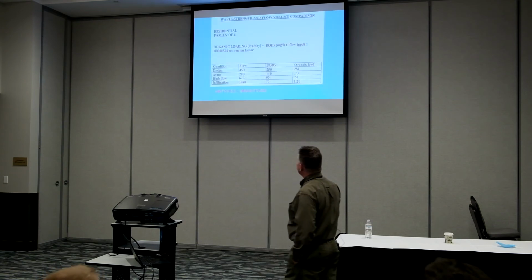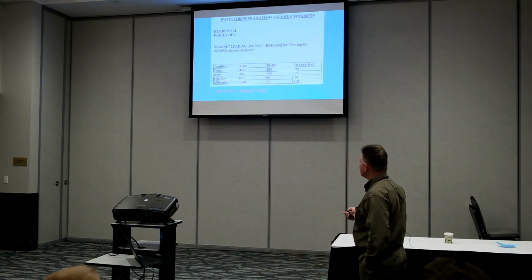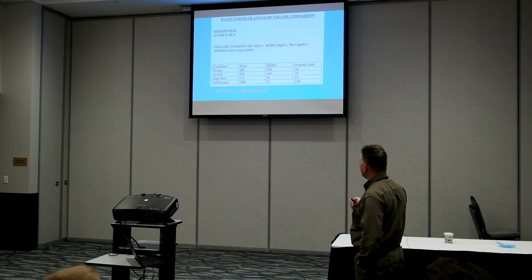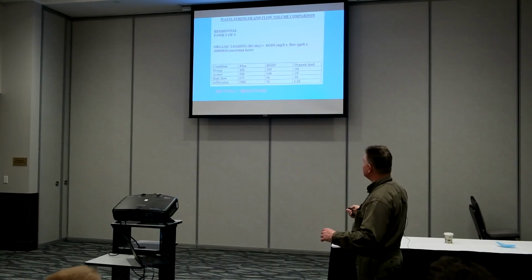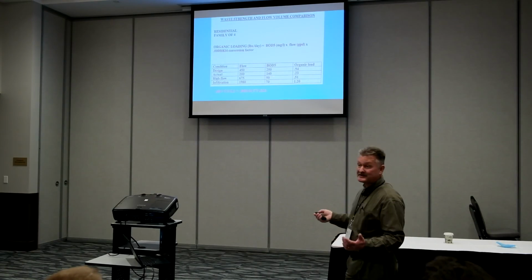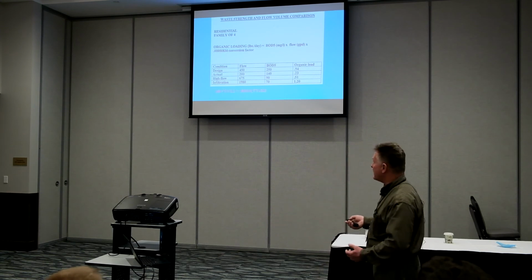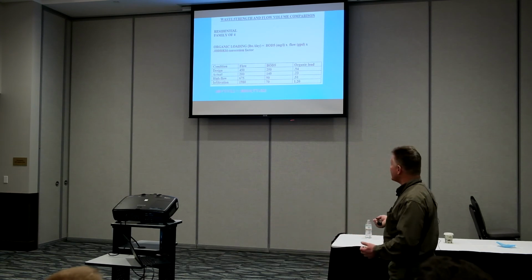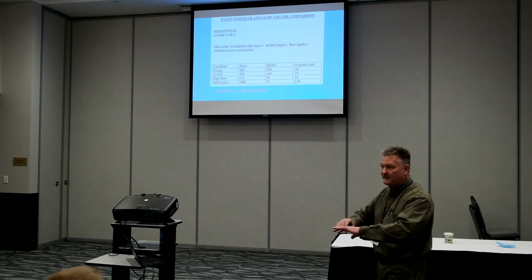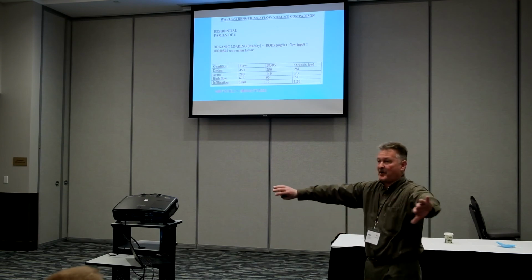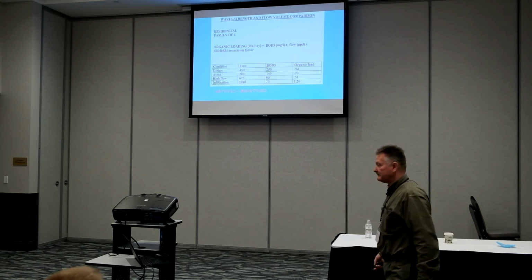So, waste strength and flow volume characterization, just real quick here. On a residential system, we know that if we're flowing at about 200 gallons a day, with typical waste strength, we've got about 0.23 pounds that system has to treat. And we know if it's properly designed and people are taking care of it, we're going to get a long life out of that. So that comes out to 0.003 pounds per square foot. So we're taking those organics and just spreading them throughout our dispersal field.